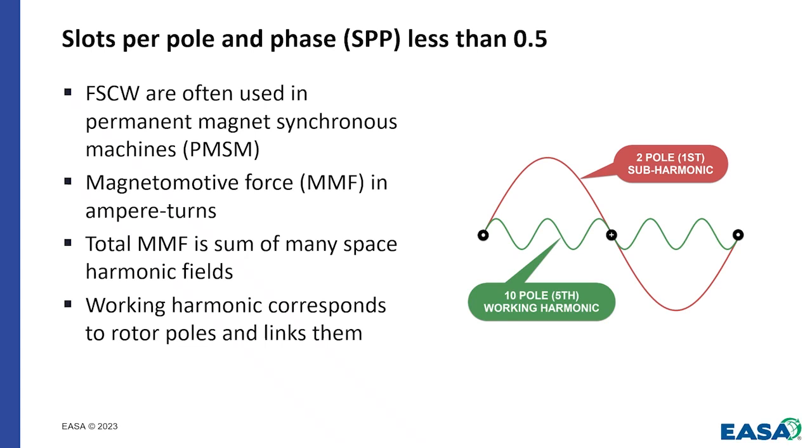So where this becomes a little bit like trying to imagine something almost in another dimension is if we have a coil and we have current coming out of one side of that coil here towards us out of the page and returning back into the page here, and we have just a two-pole coil, the magnetic field that will be formed will be of one polarity, strongest in the middle of the coil here, and of the other polarity on the other side, it will be in negative at the strongest point halfway between the coil. And that's our typical two-pole winding kind of unraveled for one coil.